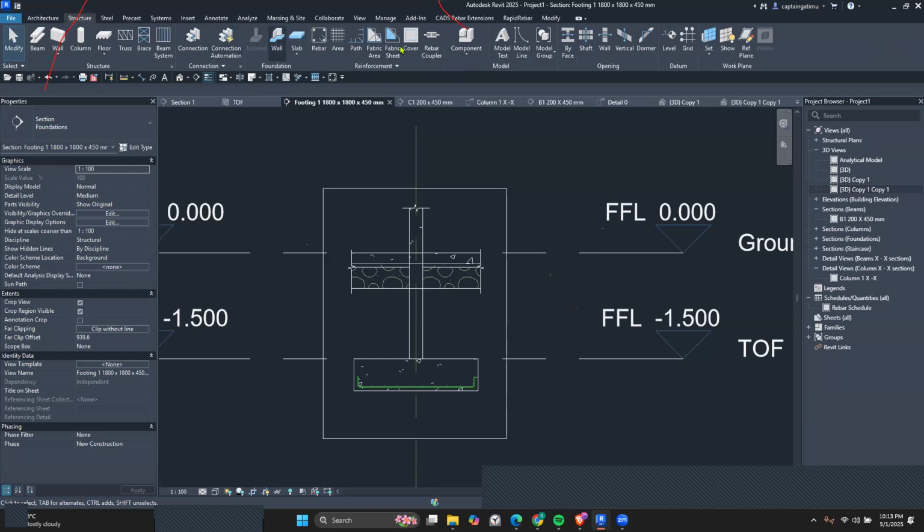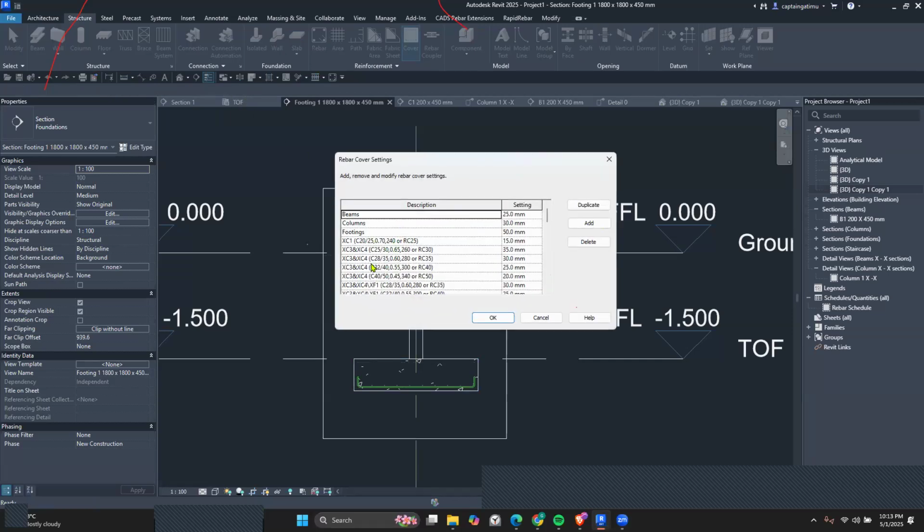Maybe you just go to cover over here and then select these 3 dots. You can delete any cover you want over here. These covers have been named after the exposure classes in the Eurocode. So you can see you have class 1, class 3, class 4. I can read through the code and see which cover probably suits your design. So you can delete this one.